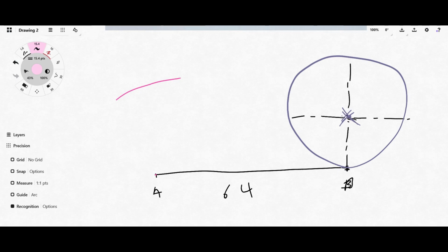You come here with your compass, and as we mentioned earlier, the distance between this center and here would be 71 millimeters, right? So you put your compass here and open up to 71 millimeters, and you draw another arc. Now you have the distance of 71 millimeters on this line, you have the distance of 51 millimeters on this line, and they all meet at a certain point.